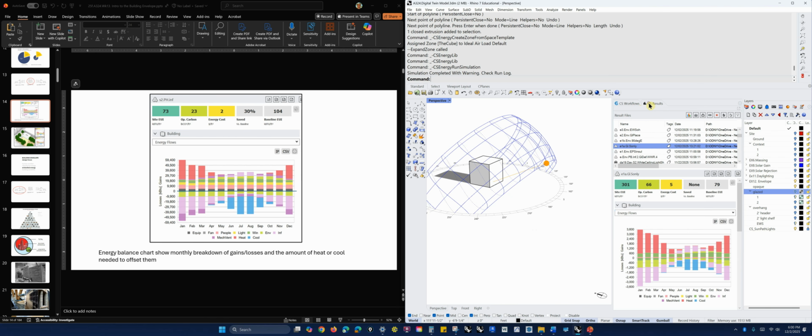Sometimes I have a lot of simulations, and if I start going into the earlier ones, it slows down. By the way, if you ever get to where you've got a lot of simulations and it's taking a long time to click on one and then another, if you just save and close down and open up again, for me, it resets the cache, and it seems like that works.